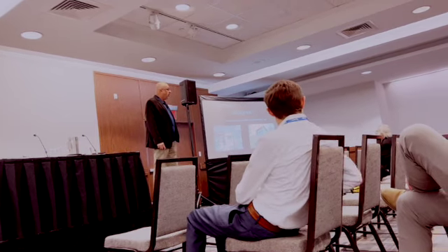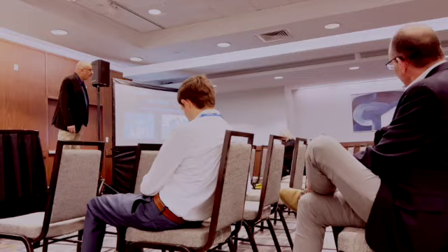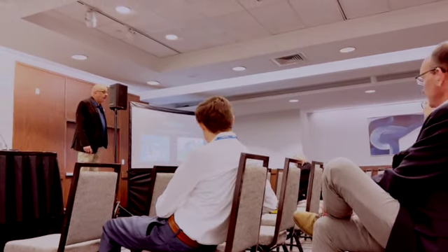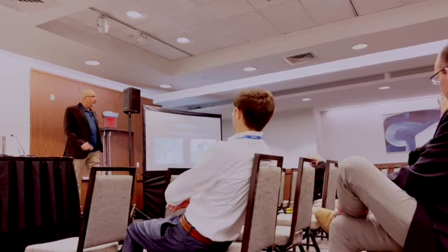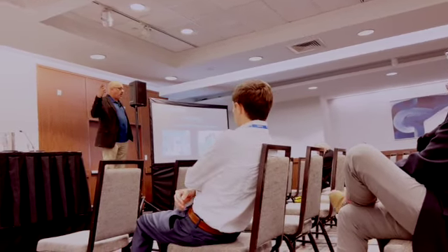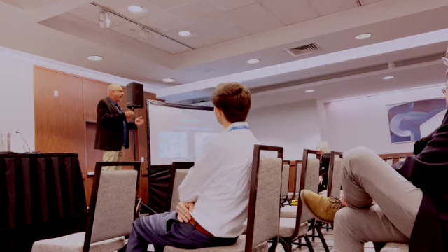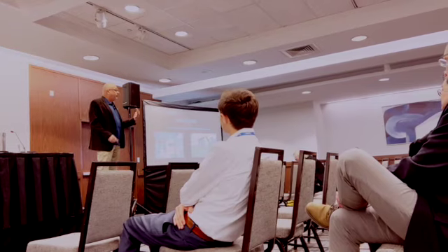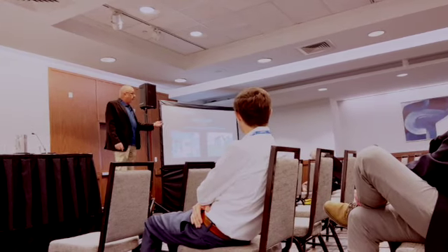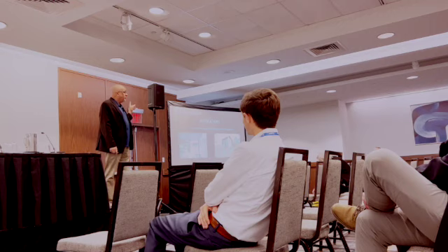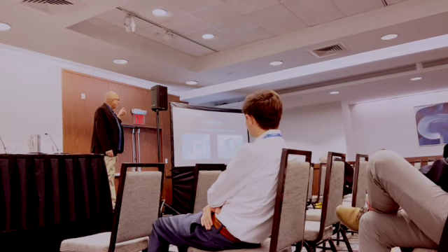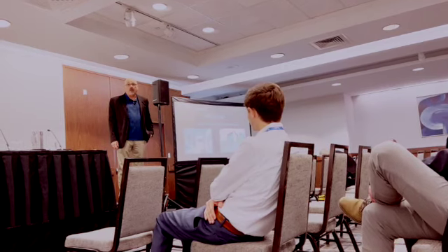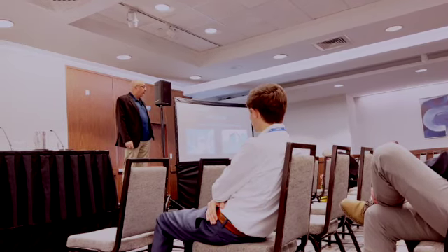Is there any physical concern about the existing wire, whether degradation or the size of the wire initially? That's a really great question. On the circuit? There's rarely a concern about degradation, except the same concern that you would have if you were retrofitting new fixtures and say, how good are the wires, mostly from a fire and safety standpoint. But what you would be concerned with is how good is the ground? Because the signals that we are using and that anybody would use in this technology require a very clean ground.